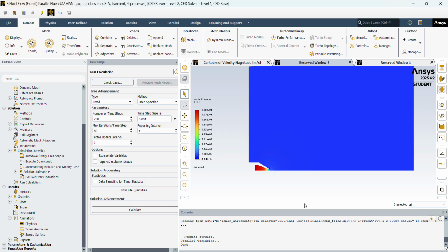Yeah, so the most important thing that I discovered doing this project was, of course, the mesh part. And for that mesh part you need to get ready while doing the geometry only. So when we start the geometry, you have to think about how I need to do the mesh. So in that geometry, if you need to make some lines or make some compartments or different faces, that's the point we need to do. And meshing is always hit and try.